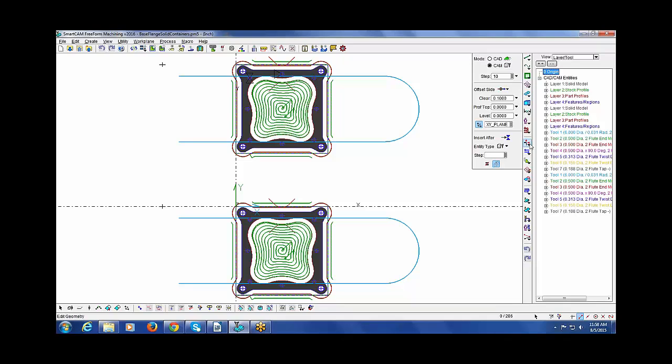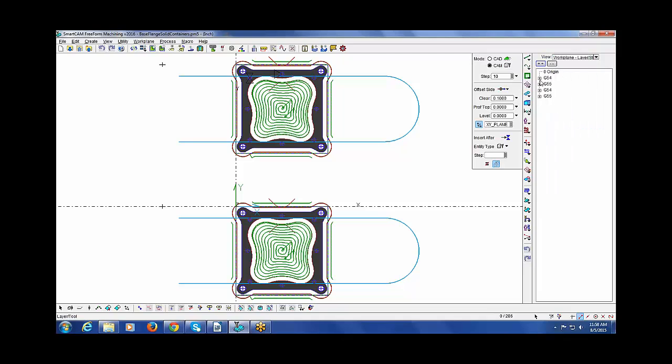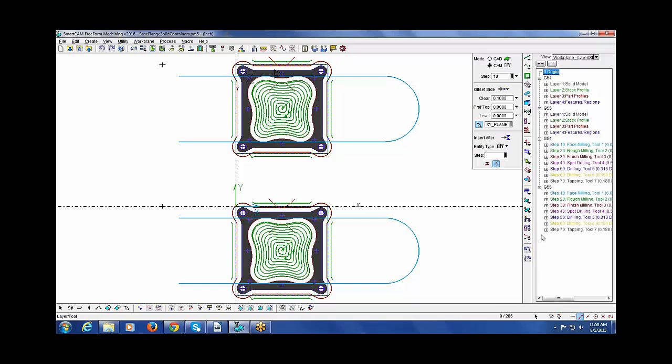But just to go further, in this case here, I've got G54 and G55 work coordinate offsets associated with these different work planes. And so we have a work plane view, and when I do that, it kind of collapses everything. And again, that gives me a real clear indication of how this model is organized. And if I was doing this in a multiple setup, I more than likely would want to just run all my toolpath with tool 1, then move to tool 2 and continue on.